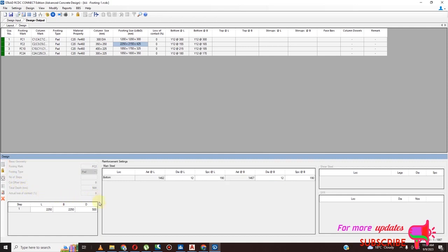Yeah, it's perfect. You can see it is giving me diameter 12 bars at a spacing of 190 and 190. So that one is very consistent, and that is what is required on the site. Something that can make the construction work easy. So I can accept this now.